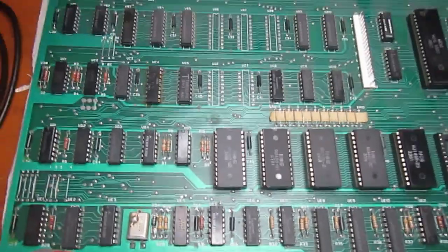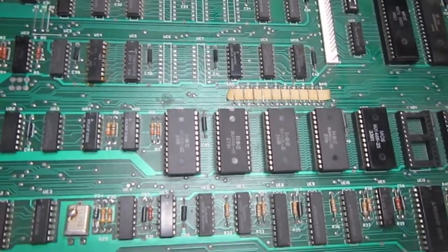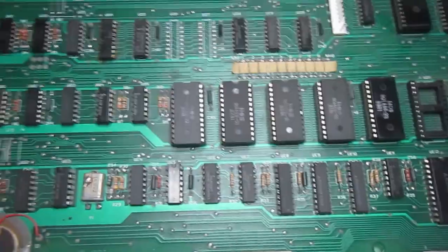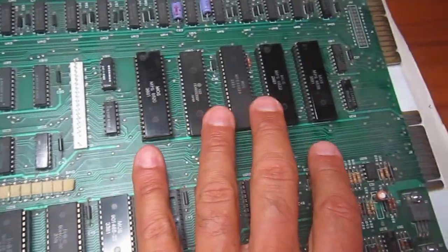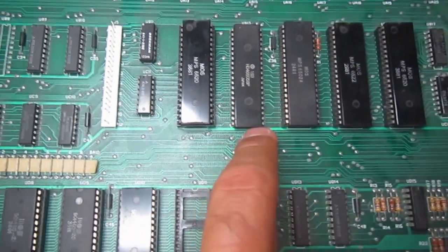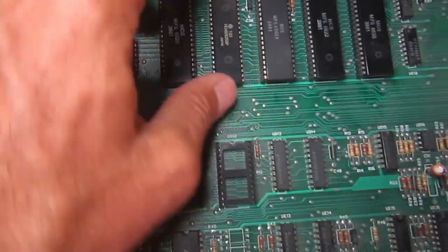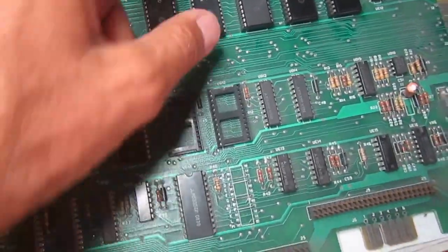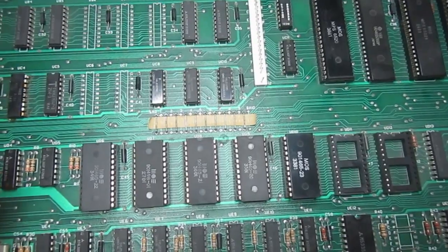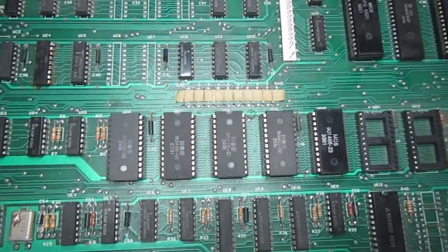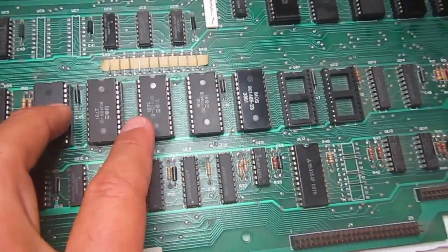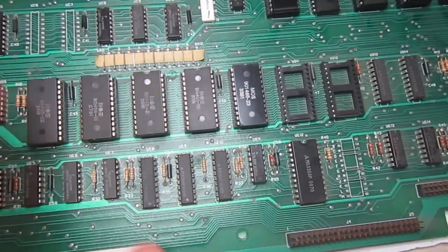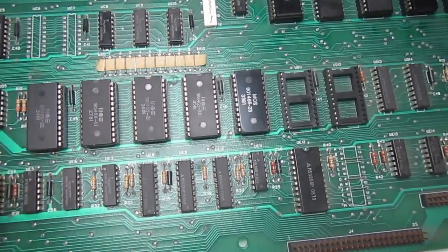This time we have Commodore PET 4032, and this one is what is called the universal board. It is the third major revision of the Commodore PET, and it has a CRT controller chip which replaces most of the discrete TTL logic that was the video interface on the previous versions of the Commodore PET. The board is arranged very differently from the other ones.